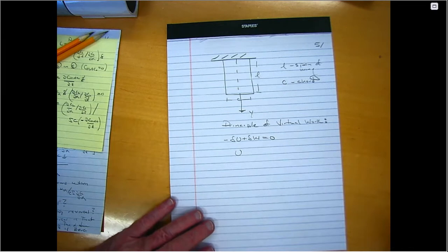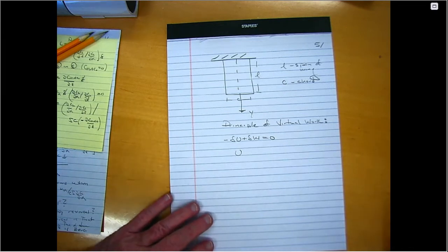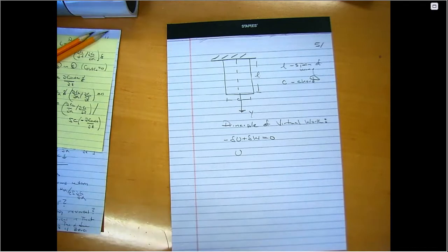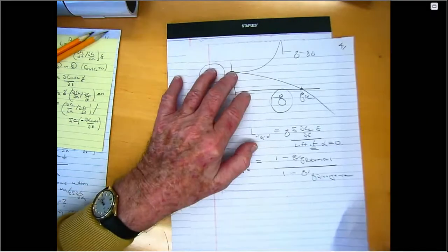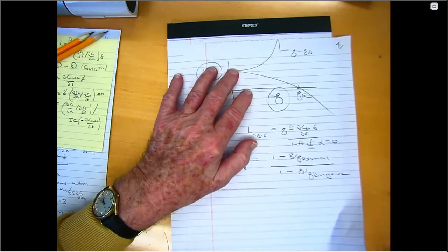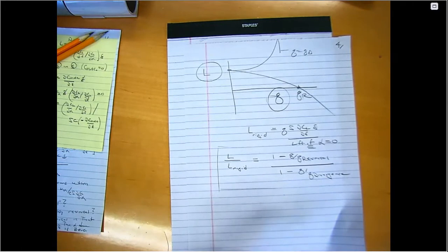Oh, this can easily be negative. It's just that that's designed. I don't want the lift to be negative in general. I want the lift to be positive. In fact, I don't even want the lift to decrease. I don't want the lift to even go down. But it's inevitable because real airplane wings are elastic. They have flexibility. They twist. And almost invariably due to that twisting,